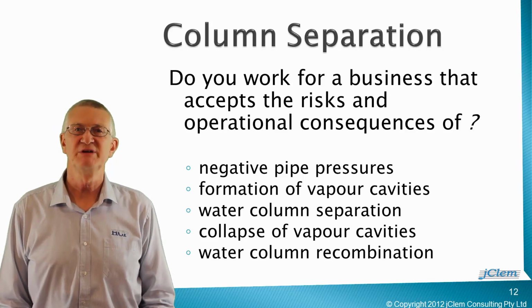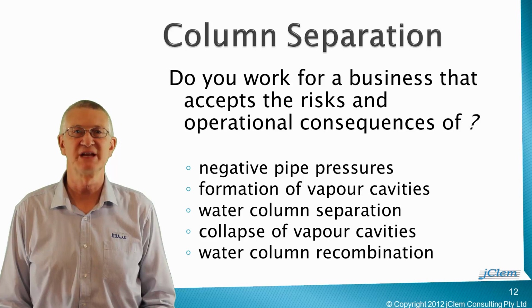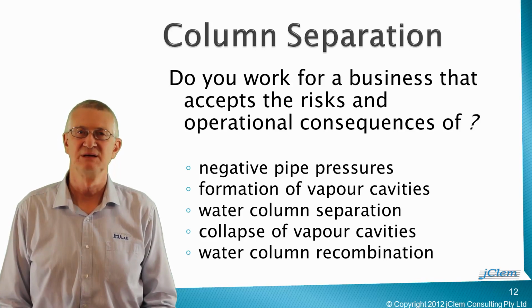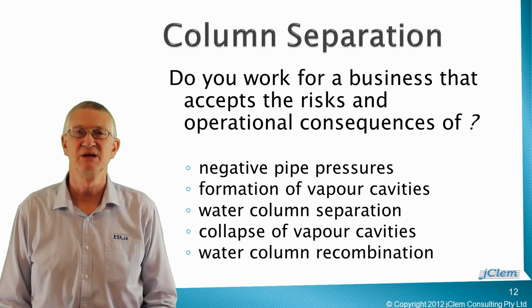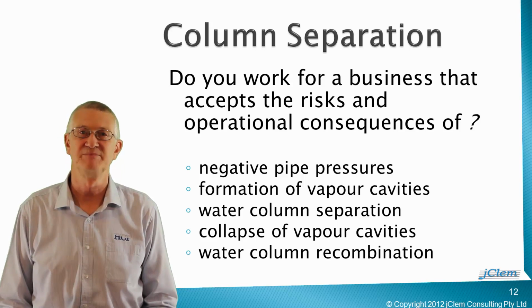Almost all engineering design teams and their clients operate to design rules that aim to avoid water column separation and recombination. Consequently, it is extremely rare that an engineering design team needs to quantify the surge heads that would occur after column recombination with sufficient accuracy to prepare a detailed engineering design.